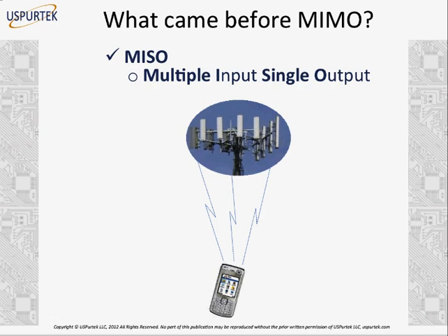So this is what the real life picture will look like. You will see cell towers with multiple antennas. And if they implement MIMO, my cell phone can tune into one of these signals. If one signal fades, the other one can be used as a backup, so that overall I have a more reliable signal. I can combine these multiple signals to increase my signal to noise ratio and my signal strength. So I can overcome my problems of fading and broken voice calls and broken links and so on.